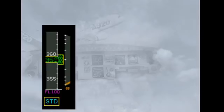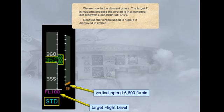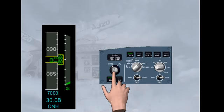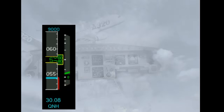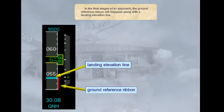We are now in the descent phase. The target flight level is magenta because the aircraft is in a managed descent with a constraint at flight level 100. Because the vertical speed is high, it is displayed in amber. At the transition level, the baro reference is set to show QNH by pushing the baro selector knob on the EFIS control panel. In the final stages of an approach, the ground reference ribbon will reappear, along with a landing elevation line.